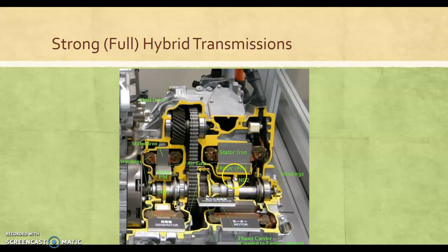Here are your bearings. There's your encoder resolver bearing. Basically this is a position sensor, and you have bearings and another position sensor right there. So we talked about that last week, the need for those position sensors. The computer needs to know where that rotor is so it knows where to put the magnetic field in the stator winding. Now these stator windings do burn up, and there's ways to test them without disassembling the transmission. I will show those later.